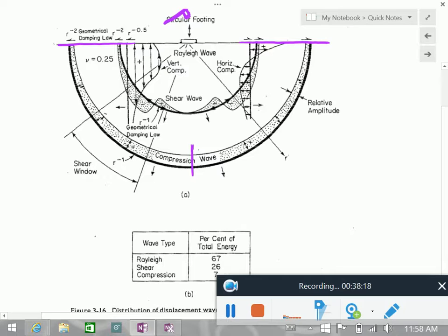What you should notice is that as you go away from the source of impact, the energy is being spread over larger and larger spheres, for example, for P wave and S wave. Because of that, since the amount of energy was constant, since it's getting spread over larger and larger spheres, the wave amplitude becomes smaller and smaller. This is one mechanism of attenuation, which is sometimes called geometrical spreading or attenuation.